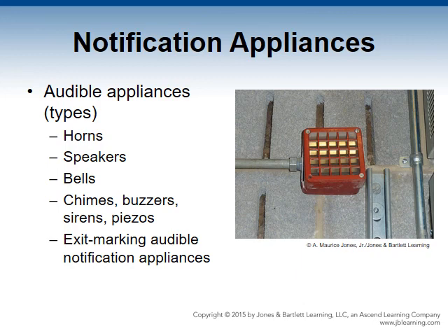Sirens are more suitable as notification devices outside or in a very loud environment. They might be mounted on a building exterior to notify building personnel or assist firefighters who are trying to locate the origin of a signal. They can be found inside where there is constant loud noise, such as a bottling plant.